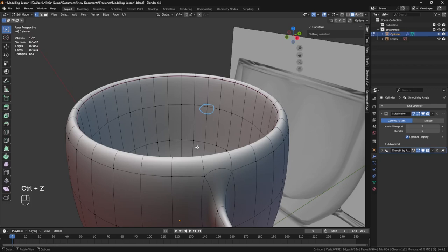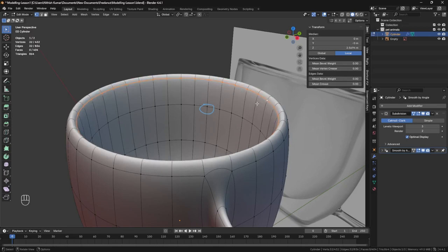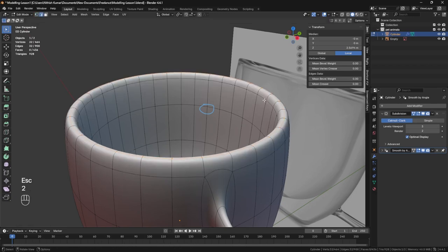Now the ideal solution would be to select the whole edge and increase the crease, telling the computer, I'm not going to create extra polygons, but make it more sharp without increasing the polygons. So for example, I can reduce it, increase the polygon count elsewhere, and still have a sharpened one. But we don't want to do that. So the ideal solution is to select the whole edge, increase the crease, and make it sharper.